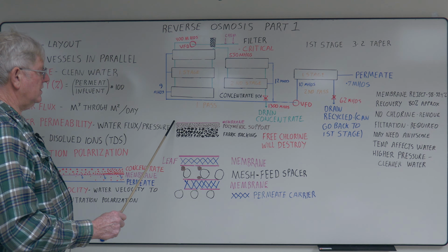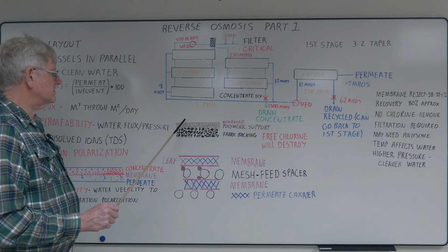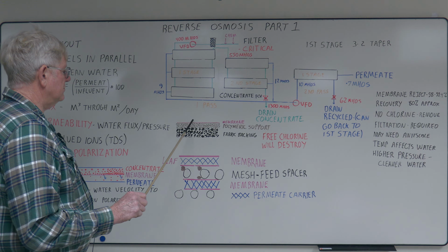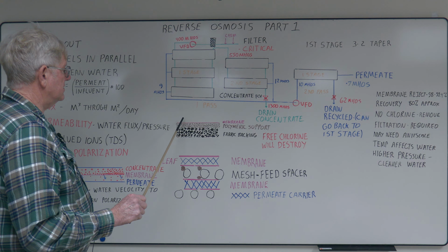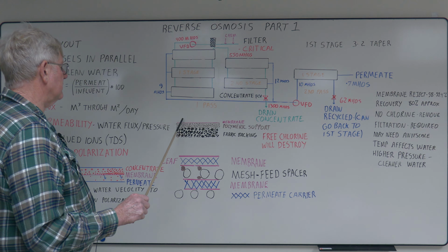This is where it can be damaged quite easily from scale particles, the mesh moving across this. That's why you don't want to slam these things with high pressure. You've got to be really careful about adjusting flows.